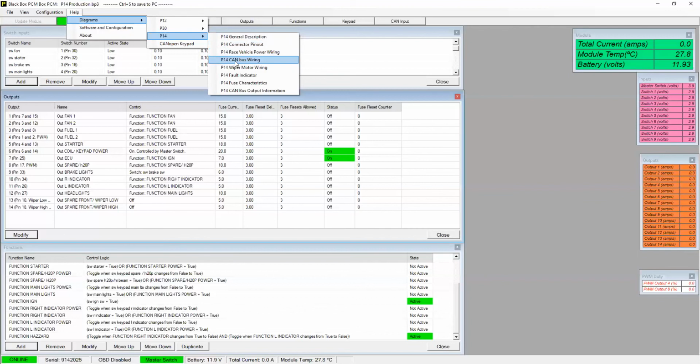The next one is CAN bus wiring. That's a pretty standard-issue CAN bus wiring diagram. It's very easy to understand. It's basically a twisted pair, and then there are terminating resistors on the ends. And that just triggered something in my mind that I should show you guys a little later for CAN bus stuff. Wiper motor wiring. This is going to give you the wiring, and you can wire in a park switch so it parks. It's just a wiper motor wiring diagram to help you understand how that works with the different speeds and inputs. Wiring wipers is interesting, but with this diagram, it's super straightforward.